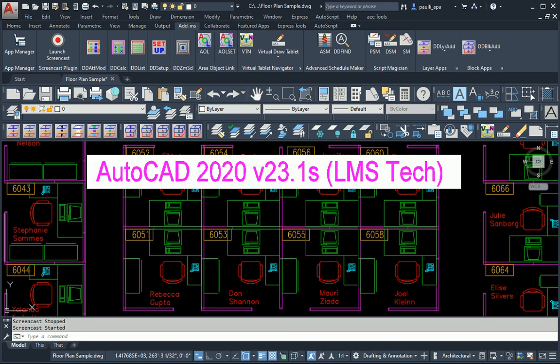This is a video that shows how to draw a circle with dynamic input and display coordinates turned on from AutoCAD 2020 through AutoCAD 2023. In AutoCAD 2020, starting the circle command, I could then select at any point intersection anywhere on the graphic screen